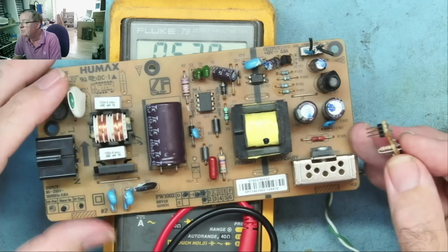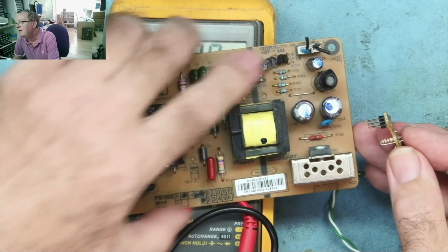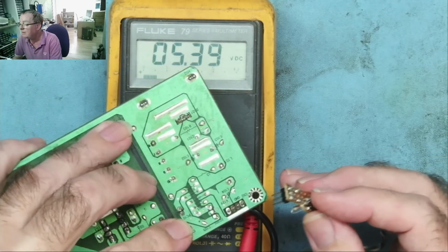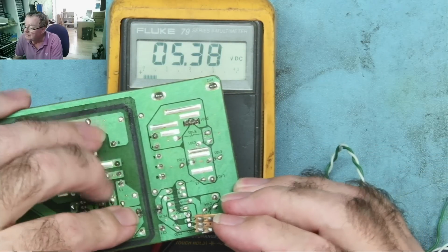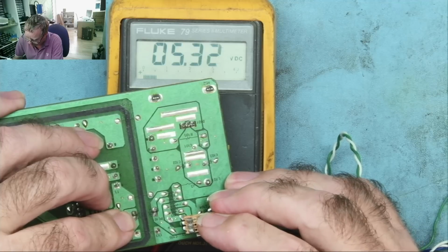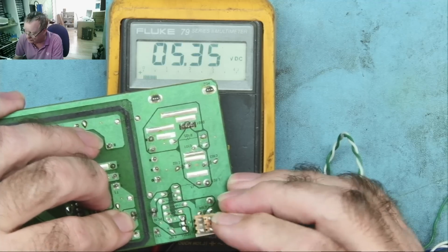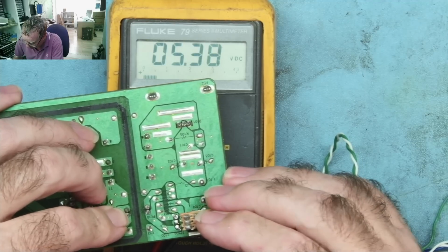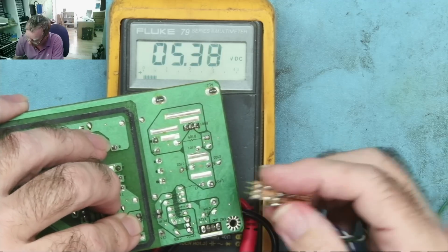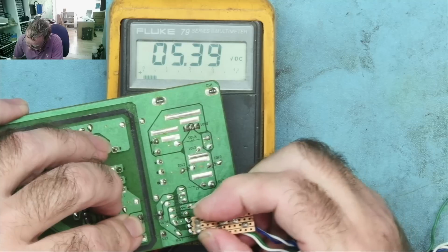So here's a little power supply we had earlier. Here is our TL431, which is the 3 pins here. Okay, so we can try it. As I say, if it reads good, it's definitely good. If it doesn't read good, you'll have to remove it and test it. It may be good, it may not. It depends on what components are around it in the circuit.